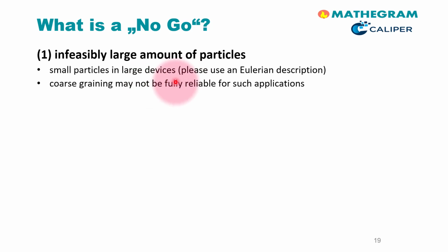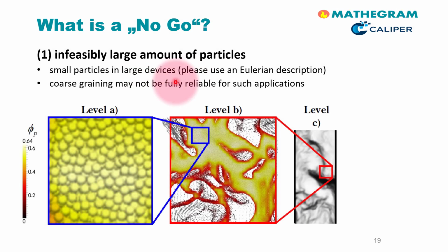and robustness. The figure here at the bottom should illustrate the huge increase of the particle count when going from level A, i.e. a particle resolved description as illustrated and discussed before, over level B, an unresolved CFD-DEM simulation of clustering phenomena, for example, to a full-scale description of a gas particle system for which we clearly prefer continuum-based models.